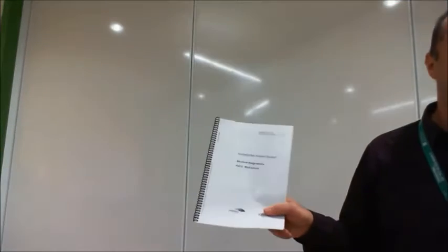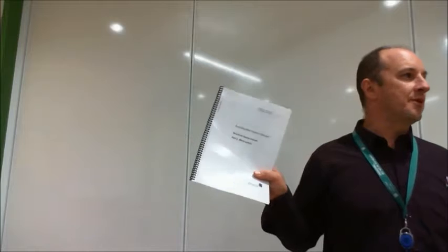This is 1170. There's also 4055, which is called wind loads on houses. And 4055 is basically a simplified version of this. And you can use it on houses and structures which are roughly the same size and function as a house. So it's designed basically for people who are designing houses. This looks pretty overwhelming when you first hit it, and so it's designed to be less overwhelming and a bit more friendly. So you guys who are doing that structure, start there and it's much easier to get your way through it.